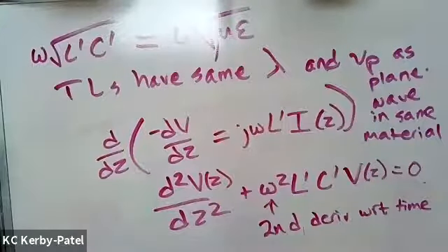All right. So we talked about how the current is not the thing that is carrying the power, right? It's not the conduction of individual charges from the source to the load. What is really carrying the energy in the transmission line is that electric and magnetic field wave.